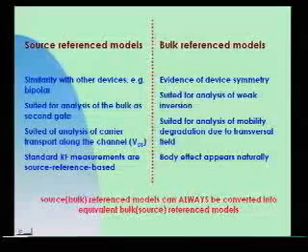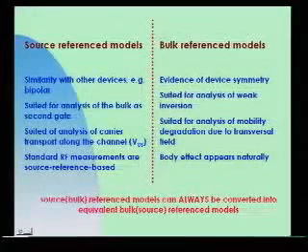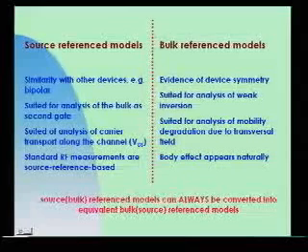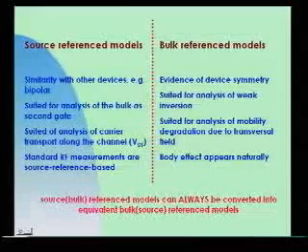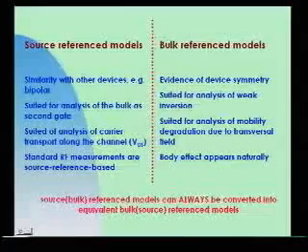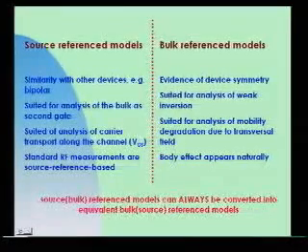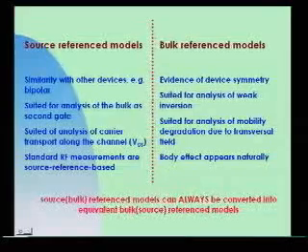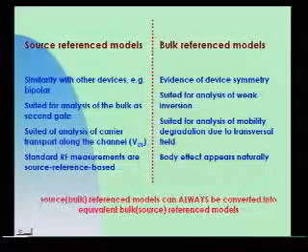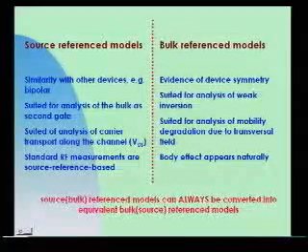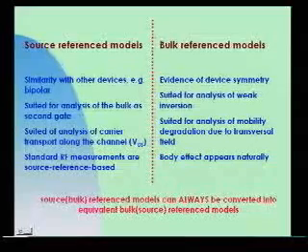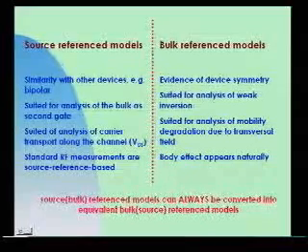What I can say about the source reference models is that it's perhaps easier to work with them when you want to compare circuits with different devices, because there is a similarity between the equations that you use in source reference models and the equations for three-terminal devices such as bipolar transistors.